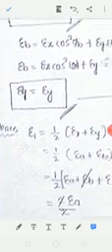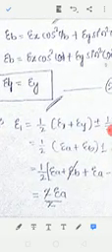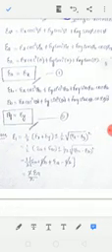So if you know epsilon a and epsilon b, I can also write epsilon x equal to epsilon a, epsilon y equal to epsilon b. This also we can write, there is no problem. Hence, already you know that the principal strains epsilon 1 equal to 1 by 2 epsilon x plus epsilon y plus or minus under root 1 by 2 epsilon x minus epsilon y square, because there is no shear strain. That's why gamma xy is 0. We have only along x and y direction. There is no shear along xy direction. So that is why gamma xy is equal to 0.